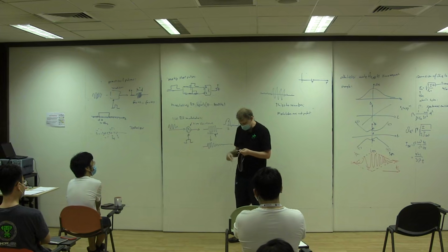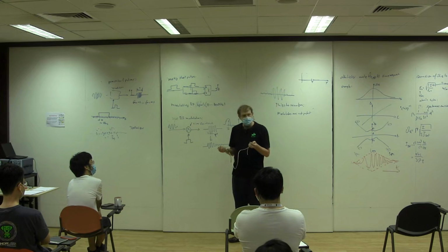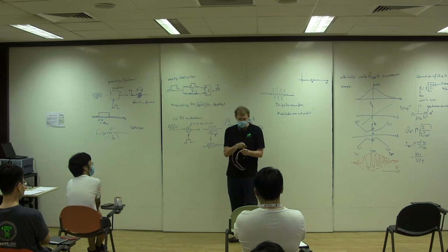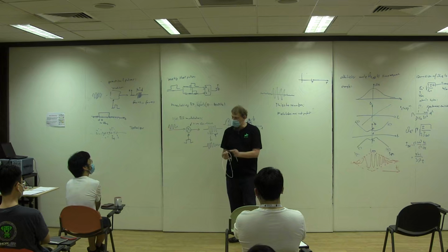There's also things that you should not forget in the lab: whenever you transmit signals, these cables have well-defined impedances, meaning the ratio between the localized current and the voltage of a signal traveling along a cable is fixed. So when you say these cables, for example, have an impedance of 50 ohm, that means the ratio of the voltage and the current of a particular form going through this thing is just these 50 ohm. Okay.